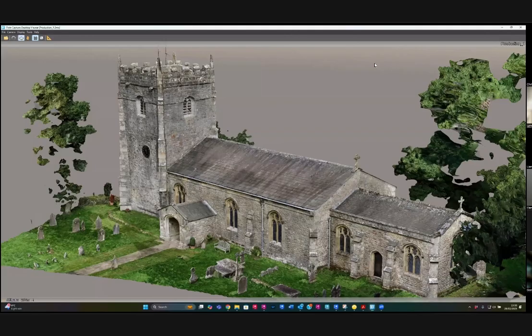And that comes into play in the offshore side, especially the surveys that are done with one eye on safety of navigation and safety of ships. If there's hazards in a shallow area, the general rule of thumb is that there's got to be a golden thread from the point that's collected all the way through to the point visualized or rendered on a map or chart, so that you can locate it and you've got the provenance of that data point.